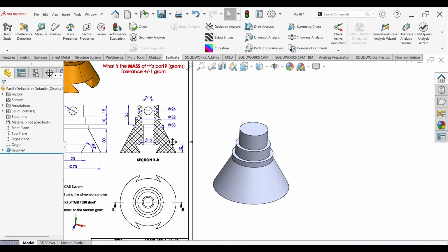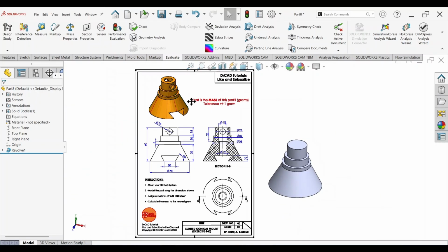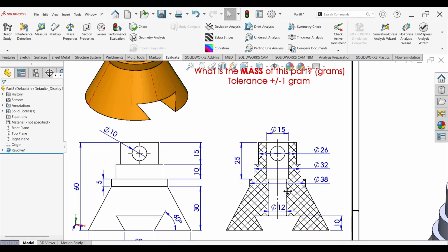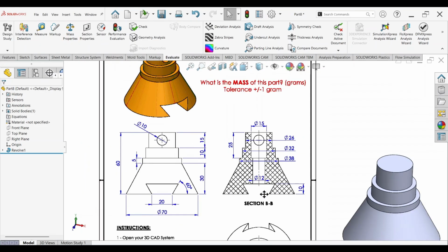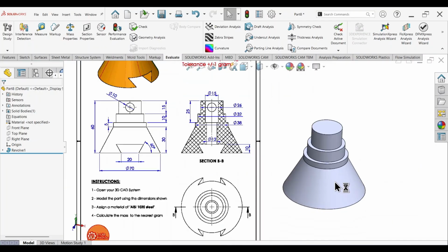All right, so now we need to create the openings for the component. If we look closely here, at least in the isometric view, we can see that there's a hole here at the top, a drill hole that runs along the component. And then we have a counterbore feature that runs all the way down to the bottom, right? And most importantly, we have a slot opening at the bottom right here. So how are we going to do this?